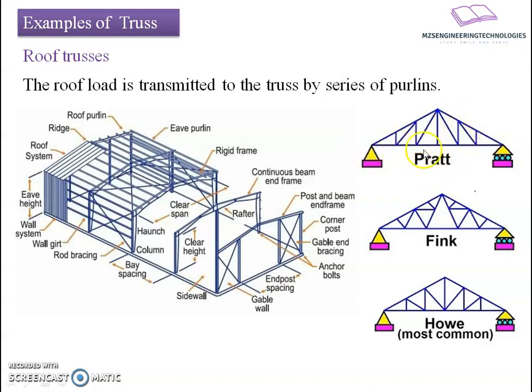Okay, so we have the bottom chord, then the principal rafter, and the vertical member, which we call a strut, and inclined members. Sometimes horizontal members are used. This combination is used to dissipate the forces which come through the member action over the large span.